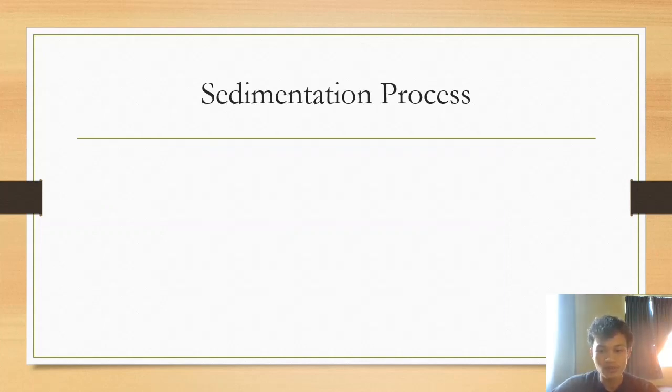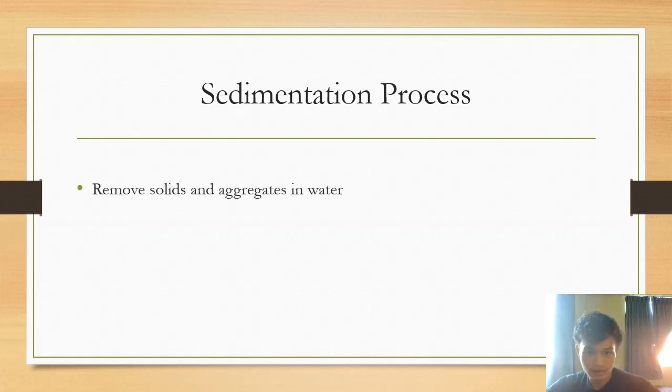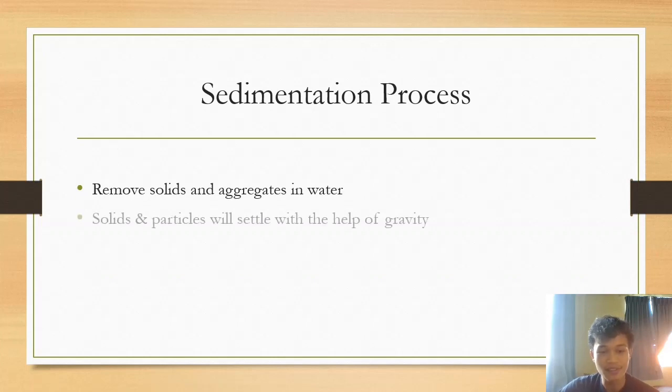So the next process is called sedimentation. This process involves removing the solids and aggregates that have bonded from the previous process. The large and heavy flocks after mixing will move to this tank, and in this tank the flocks are allowed to settle inside the tank with the help of gravity.